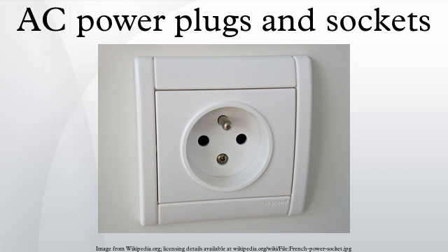Prior to the adoption of the NEMA standard, a plug nearly identical to the 2-20 was used for 120 V at 20 A. That obsolete plug would fit into 5-20 and 6-20 sockets, which supply different voltages, but will not fit in a NEMA 2-20 socket.